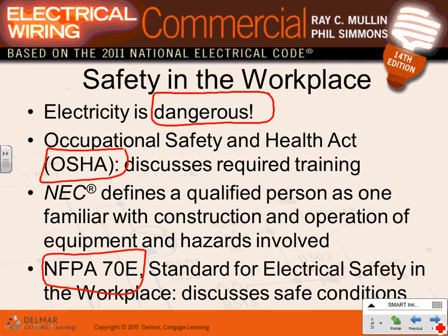Now, could an arc flash happen while I'm taking my pictures and taking my measurements? Yes. So you are around electrical equipment. When you work as a designer, you are not licensed, bonded, or insured to open or work on an energized or non-energized electrical system. We don't carry tools unless you are hired as an electrician. I was a master electrician at that time, but I wasn't hired by Bloom Engineers as a master electrician. I'm an engineer. So we're not bonded or insured to do electrical work. We're bonded and insured to do the design part. So be very careful with that one.